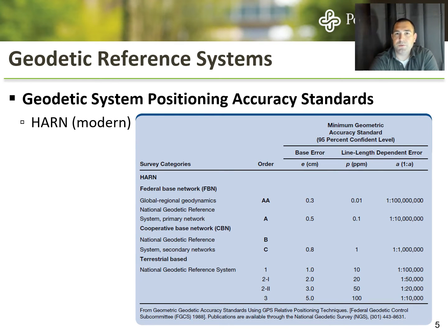And when it comes down to the accuracy and the precision with which we do that nowadays, it's pretty mind-boggling compared to where it was just 50 years ago. So the advent of GPS and these high accuracy reference network systems, HARN, it's pretty incredible. So some of these errors are 1 part in 100 million. Especially with a long enough amount of time and a sophisticated enough processing unit, you can get pretty incredible accuracies when it comes to setting the reference network for these geodetic coordinate systems.